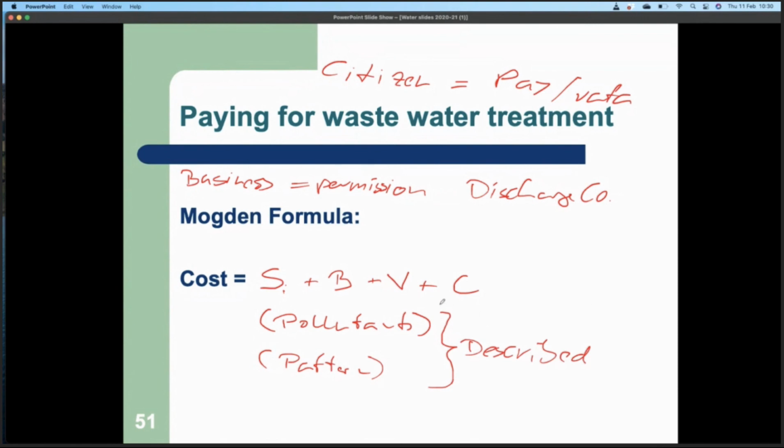So the wastewater treatment company, actually in the UK, is also the regulator. So the wastewater treatment companies are also the wastewater regulators. In their discharge consent, they will not only tell you how much you pay for the stuff, but they will also tell you the sort of other parameters and limitations to the discharge consent that you get. So for pollutants, they will tell you which substances you are not allowed to discharge at all, or what the maximum concentrations of chromium may be in terms of concentration, absolute discharge, relative discharge, as in how much concentration do you have on any given day.